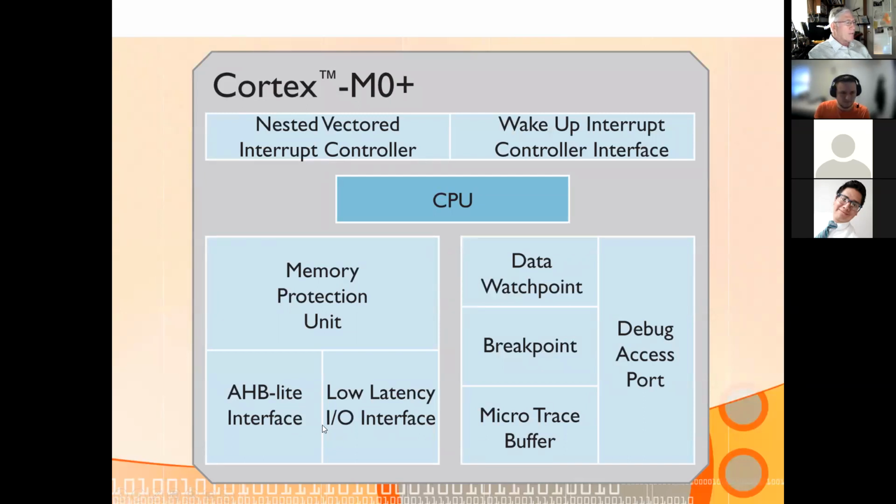That feature involves using the actual address of the GPIO pin or port to have included in it some bits within the address that are not actually used for the address, but are used to transmit specific instructions about what to do with the bits that you're addressing. And that's called decorated stores and loads.